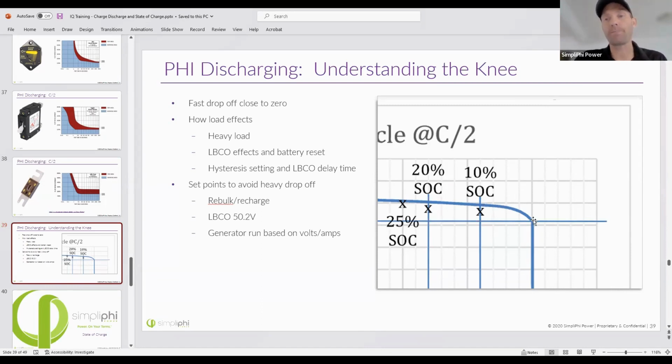Discharging to 100% depth of discharge, you're really only looking at around 3,000 to 3,500 cycles if you cycle all the way down to 48 volts every time. Discharging to 48 volts 100 times is not going to cause major problems, but batteries are most vulnerable at their greatest depths of discharge and their highest states of charge. High voltages on the battery during a charging cycle are the dangerous parts, and then discharging beyond the rated voltage of the battery. So you don't want to discharge your battery below 48 volts.